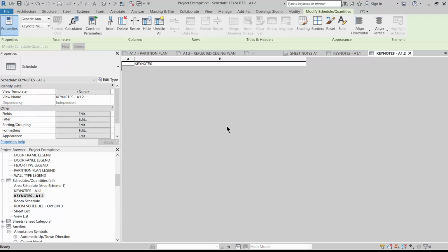and then have all of the filtering in place. So then when you start keynoting, you can just bring up the symbol, make sure it has the correct filter, and populate your text as you need to create a note. This is why this is preferable over just creating text and on the title block and the notes, because then you have to go back and forth thinking about, okay, this is the text that I want to type, this is the note, and making sure they match.